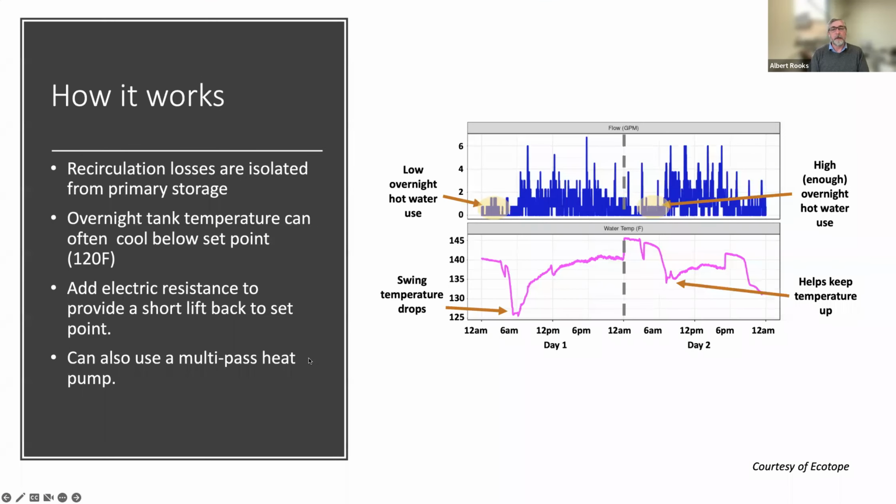And when we size a new building in some of the sizing tools that we're going to look at in a little bit, it will give us a prediction of how that swing tank's going to behave. So real building, these are real results, similar building in Seattle.